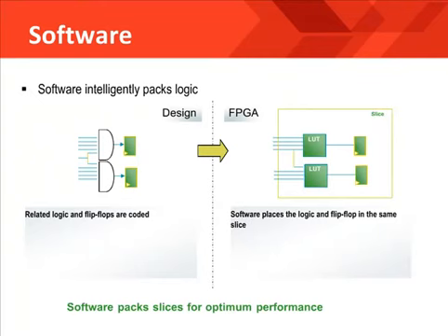The reason this is necessary is the implementation tools can only pack related logic together in the same slice, since there are a limited number of inputs to each slice. This is important with registers since all of the flip-flops share the same control signals. Likewise, if the tools are going to use the 5-input LUT configuration, it has to be able to find another combinatorial function with 5 of the same inputs to be grouped into the same slice. You see, it's all about grouping related logic into the same slice. If the tools can pack related logic together, it does not end up wasting LUTs and registers.